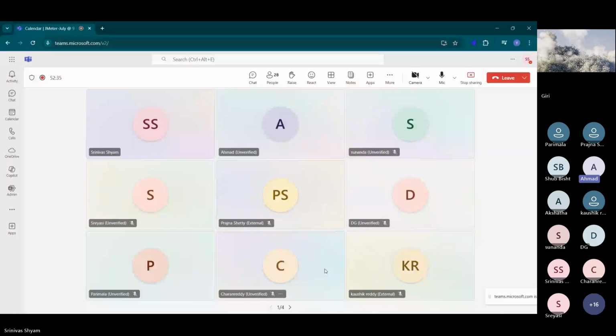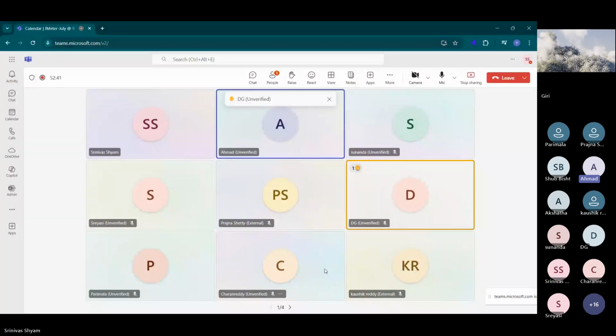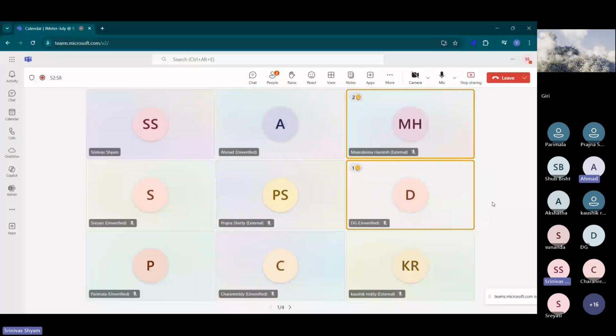No, I think it's all good going. Just one quick thing. You have considered 40% of the users for endurance. So on what basis do we have that 40%, or is there any kind of standard? It's a general rule of thumb we follow. You will never run an endurance test with the same load.